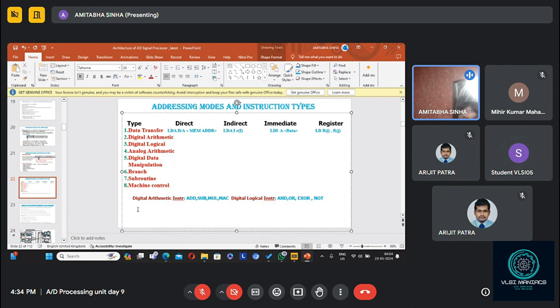Okay. Interrupt could be hardware or software. So if there is a hardware interrupt, it means some external device wants to get the attention of the computer, the CPU. It gives a signal here, and the CPU, after receiving that signal, allows the processor to go to a particular location. So, call on interrupt.